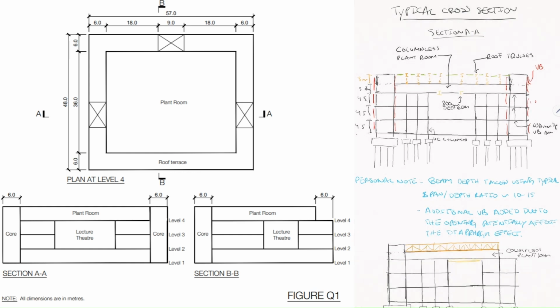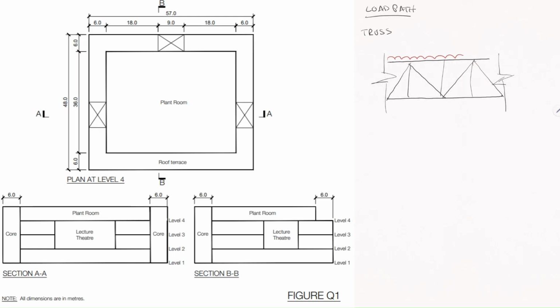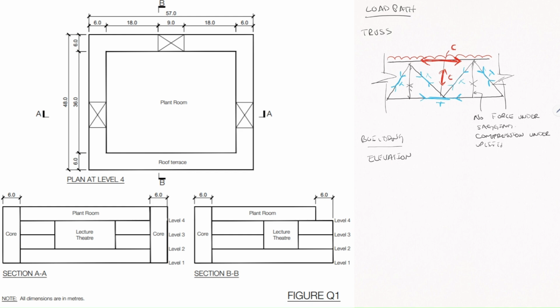Whenever I have a truss, I tend to show the load path, showing what parts of the truss are going to be in compression and what parts are going to be in tension, and in this case, which parts are not going to take any load. And I noticed that one of the nodes just didn't make sense, it wasn't in equilibrium. I had shown two of the diagonals in tension. They shouldn't be in tension in this case, so I changed them later to be in compression.